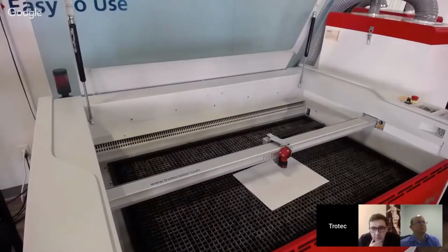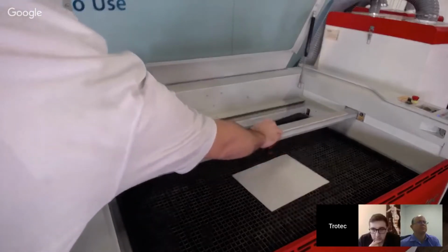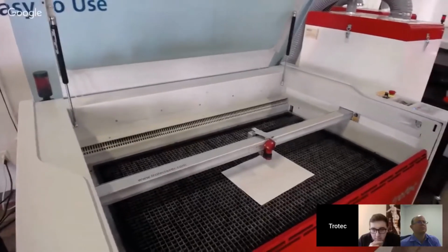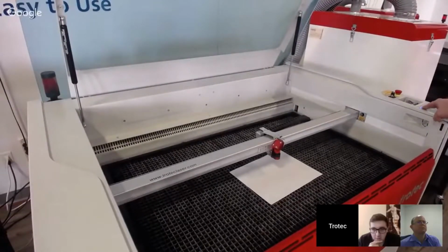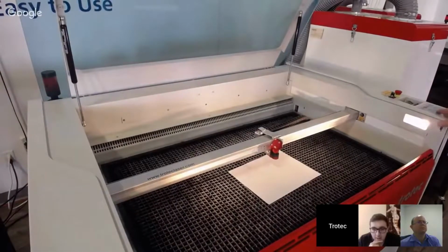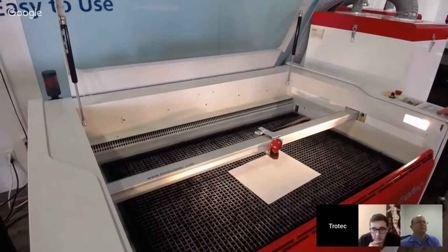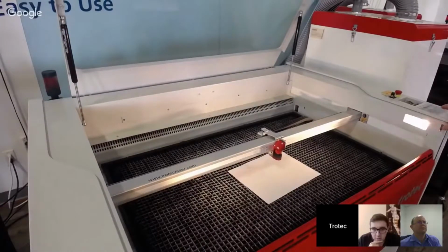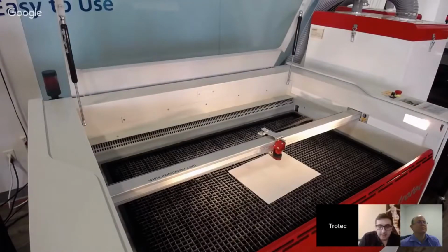Oh, wait, Anthony, sorry, before you go back, can you show them the keypad as well, that you can move the head with the keypad, not just manually? Yeah, we can show you that. So right now our laser's in standby mode, which allows us to move this around freely, which is great. Or as Lev was saying, you can come here and take it out of standby mode using the power button. And now using your D-pad, your directional pad on your laser, you can now move your laser like so. Yeah, and you want to make sure not to move it when it's not in standby mode, like manually. That's correct.